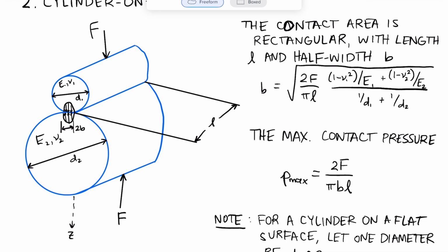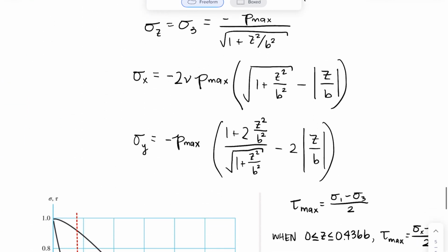Now, once you have a contact stress case with friction that provides shear, these equations will change. Some common applications of that would be the wheel-rail interface when the wheel is actually moving, and also gear teeth. You are always going to be applying some shear due to friction.